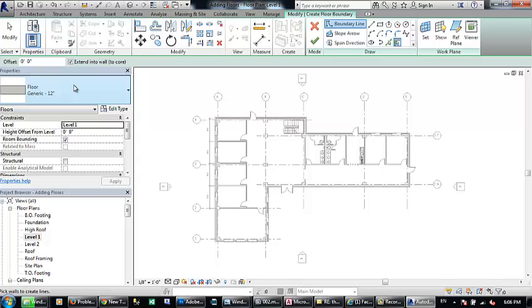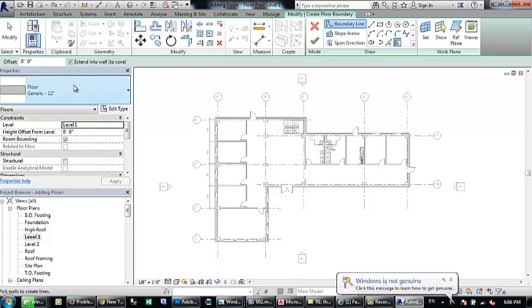So it makes sense that Revit asks you to extend the slab to the core, not the wall. It's asking whether you want to extend the slab to the core, because the core is the thing that carries the slab. Suppose that this is our slab here. If you want the slab to rest on something, you have to extend it to the core to rest on it. You don't extend it to the wall.